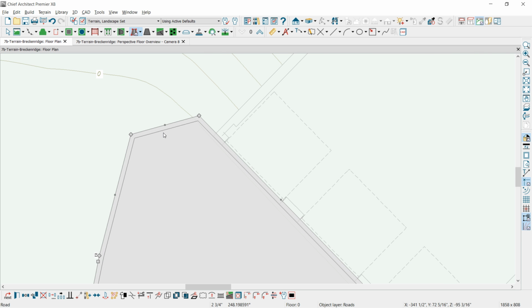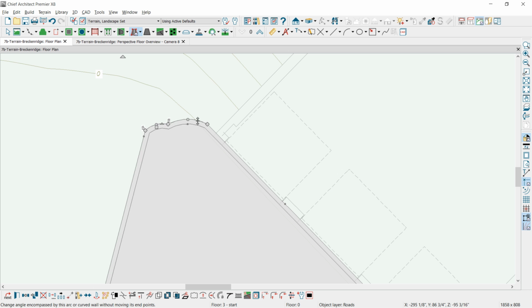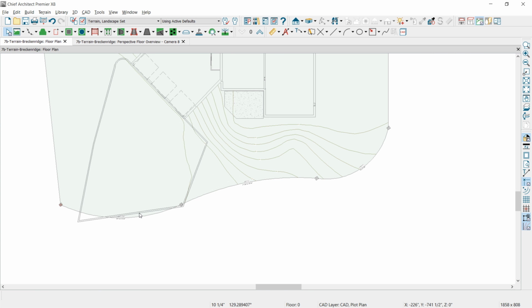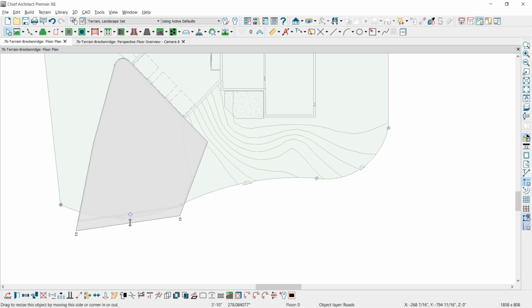And I'm going to have another break. I'm going to use the number 3 on the keyboard because I want to kind of have this be a semicircle. I'm going to pull this over with this selection highlighted. I'm going to create an arc out of it, and I'm going to do the same thing. I'll pull this over a little bit. I'm going to do the same thing on this segment here, create another arc, and that way we can kind of use this and make a nice smooth area in here. Zoom out, and eventually I'll come in here and clean that up.